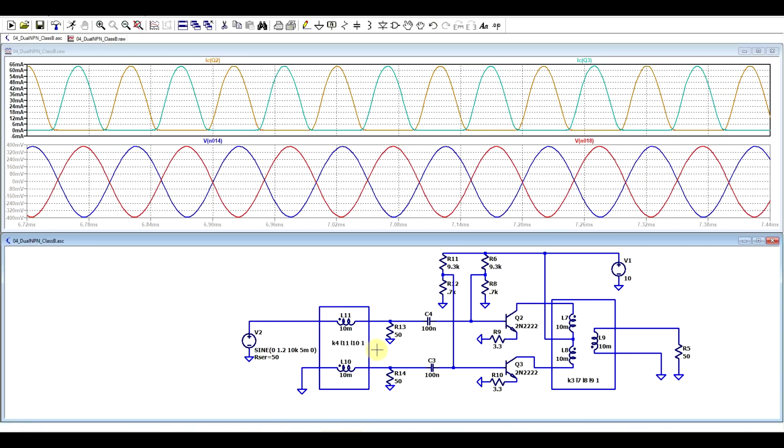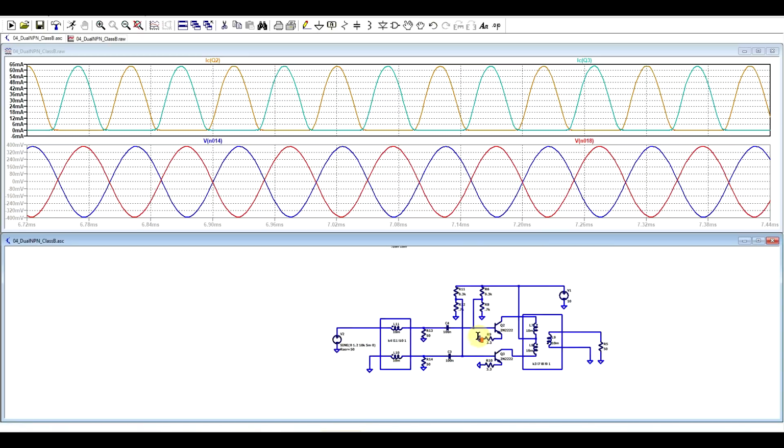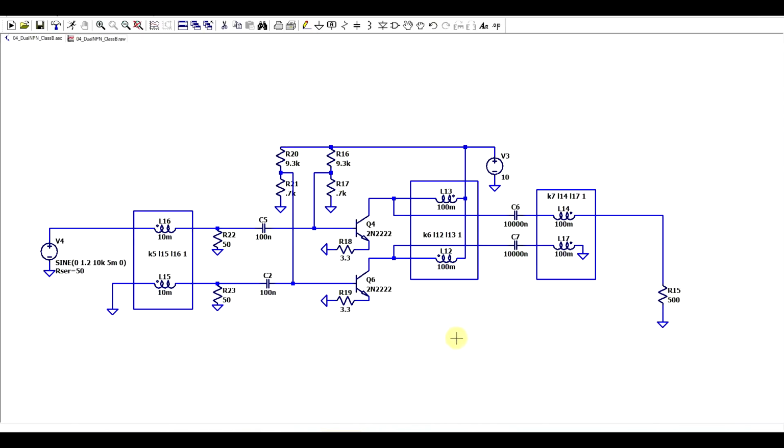Now, we can also take a similar approach with the output side. So another design to look at looks something like this. Here I left the input side the same, with this two-winding transformer, but then on the output, rather than having the previous transformer, I used again two double-winding transformers. Here one transformer is used to supply the two transistors, and the two windings are wound in opposing directions. Then the two signals are recombined using another transformer, similar to the way in which they were split up on the input side, and then this goes to the output.